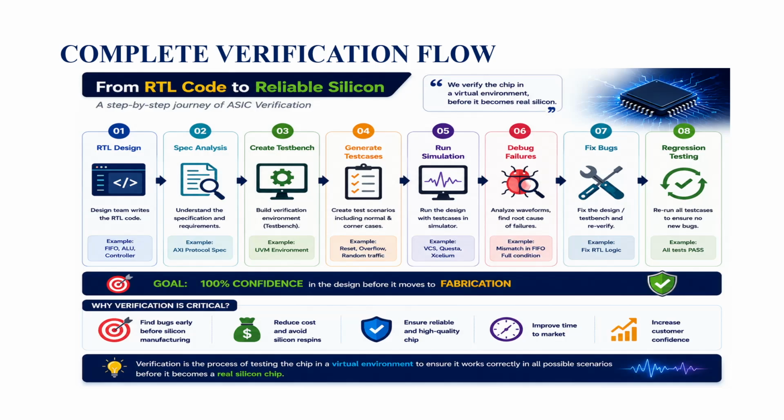Is my RTL supporting proper reset? Whenever reset goes low, whether all the signals are getting generated, whether it is generating all the values or not. Whenever reset is high, all the signals have to go low. I need to check whether it is performing properly or not. That is the first foremost thing I need to check: clock is generating and reset is working properly or not. That test case I have created and I have to run the simulation.